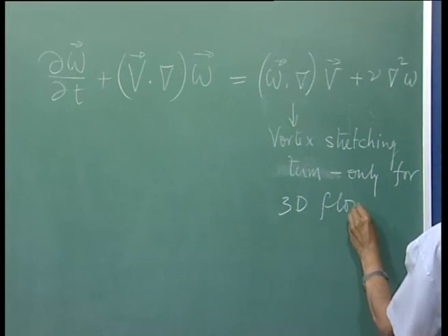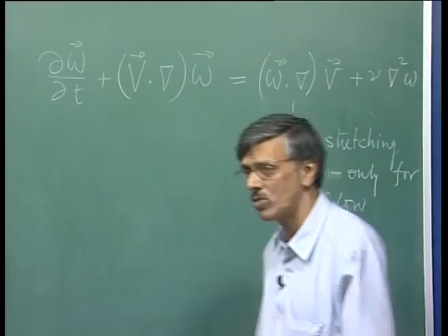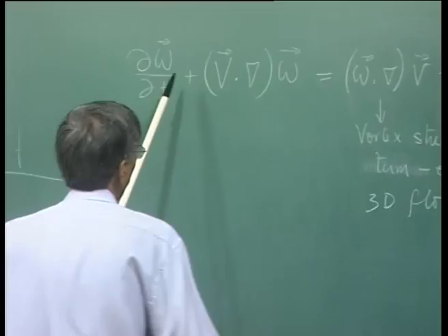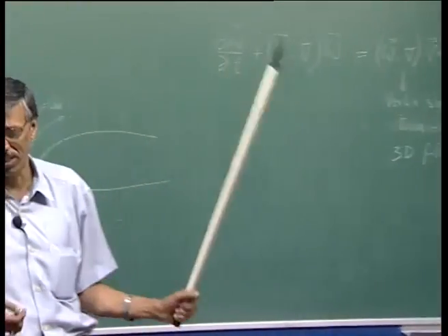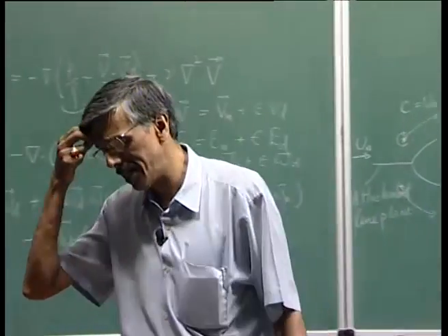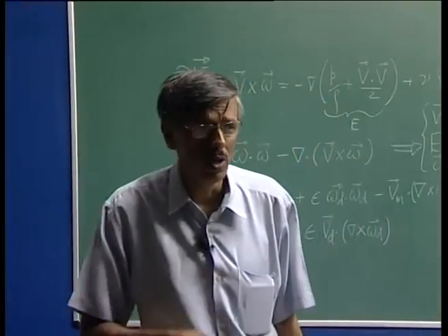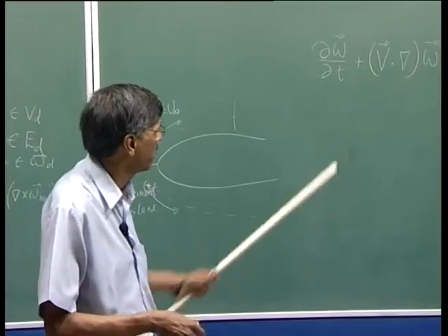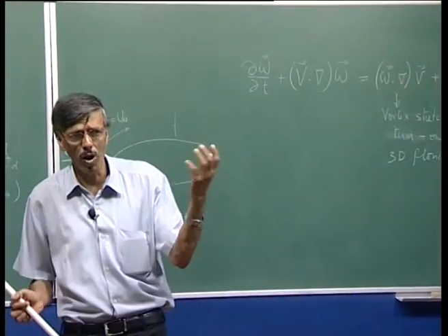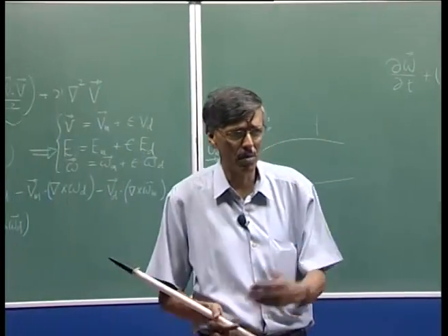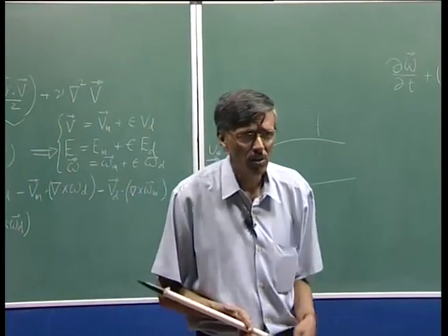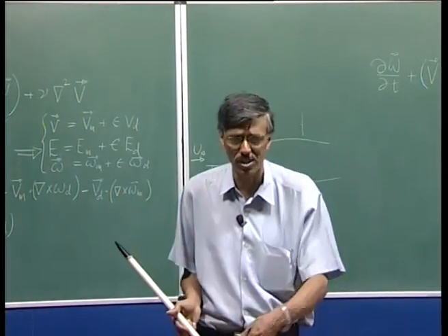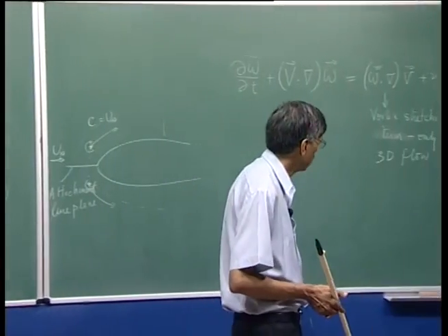This observation, the splitting of the vorticity transport equation in this form, was very elegantly used by Kolmogorov and his school, where they showed how energy cascades due to this nonlinear term, from small values of wave number to large values of wave number. We'll come back to that discussion in the second part of the course.